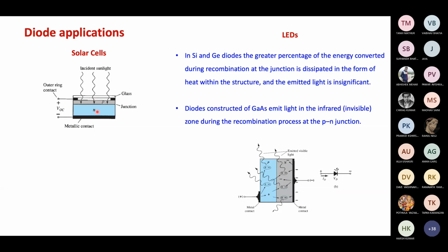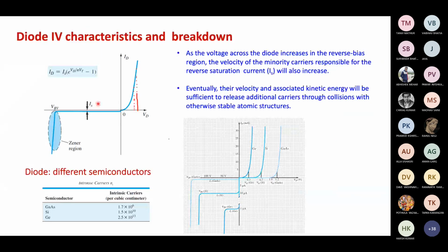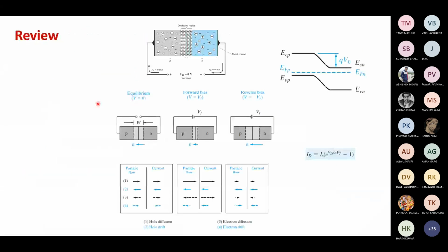If we have high doping on the N side, then almost all the P side will be depleted. Generally in junctions, if we dope one side very heavily, for example the N side, and the P side is lightly doped, the depletion region will be more in the P side. Sometimes the entire P side might be depleted.